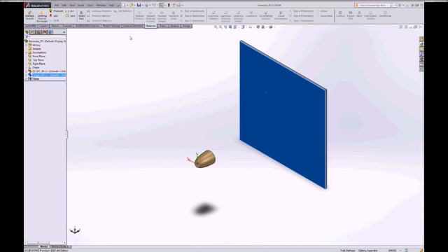Within a SOLIDWORKS part environment, you can apply media, you can apply coatings. However, when you're defining sources, doing ray tracing, analysis, design, etc., you must be in a SOLIDWORKS assembly. That's why these options were not available when I was creating my part geometry. So if you want to do ray tracing, you have to be in the assembly environment. But it is a standard SOLIDWORKS assembly file, nothing special about it.